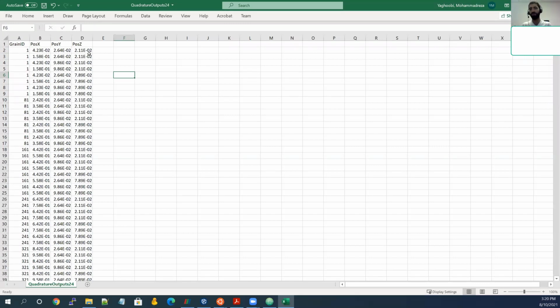So if there is any other variable you want to output for each integration point, this is how. Last session we had a question regarding what someone should do if they are trying to average the stress in each grain. The handy way to do that is just to output quadrature of those integration points with the grain ID and the specific stress component you are interested in.